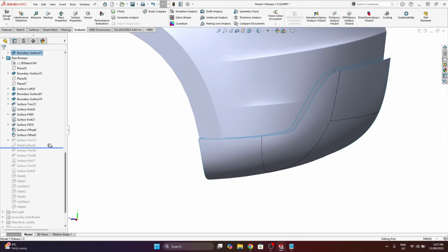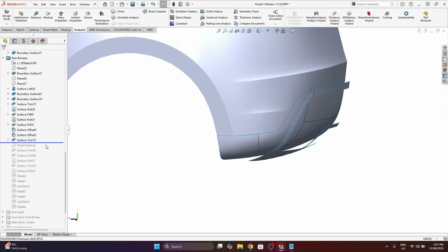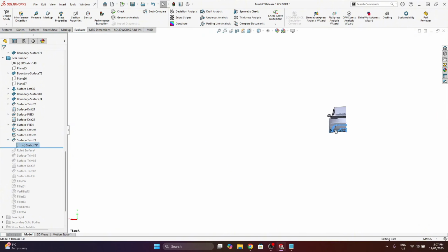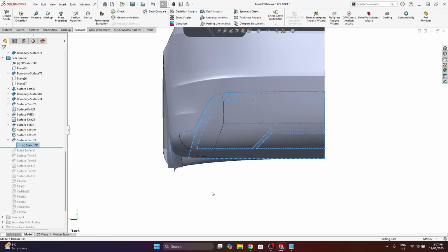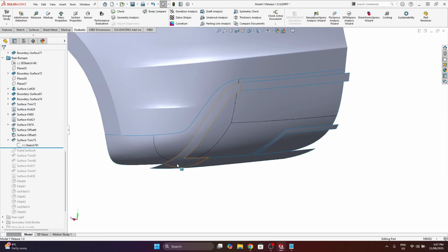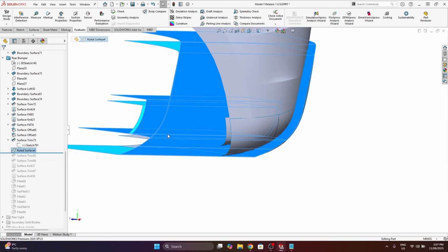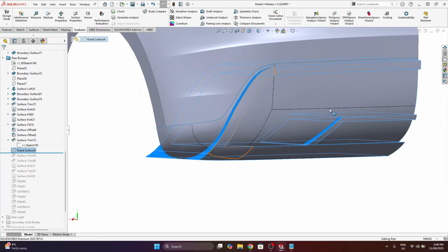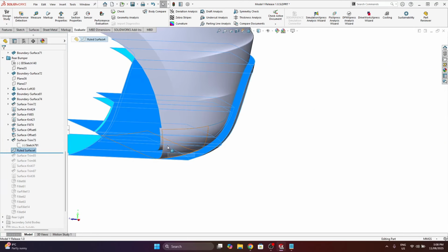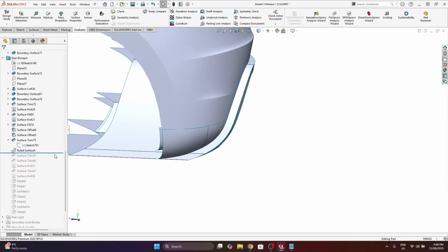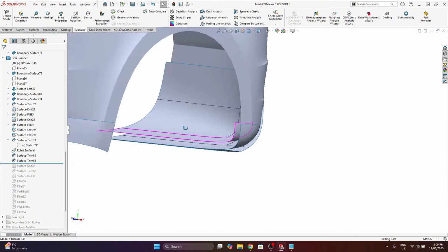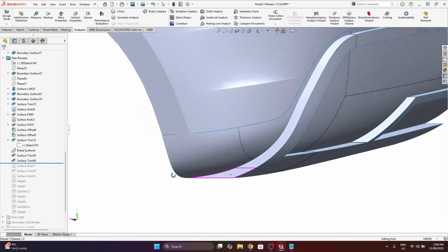And then I'm using a trim, guided from a 2D sketch, to cut away the regions I don't want. Here I did a ruled surface and sent all these edges backwards to intersect through the original surface. Then I did a surface trim to bring it back.